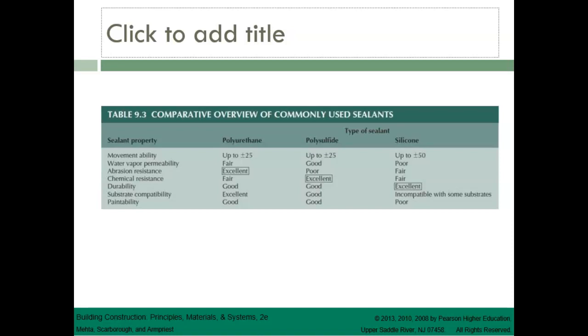Polyisobutylene has excellent resistance to water vapor transmission. Therefore, it is commonly used as a primary seal in an insulating glass unit. The secondary seal in an insulated glass unit is provided by the silicone sealant because of its durability and good adhesion.